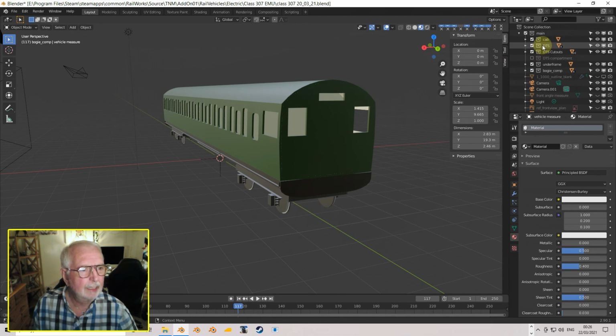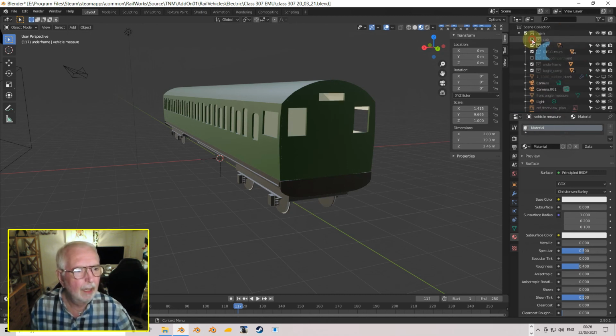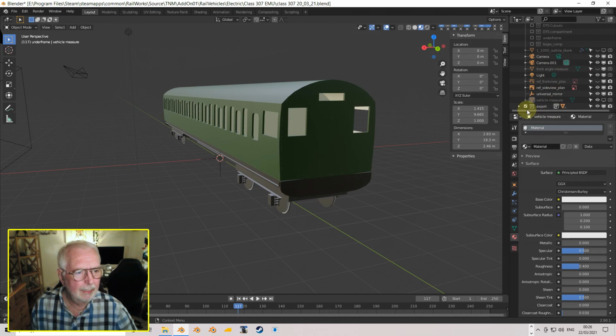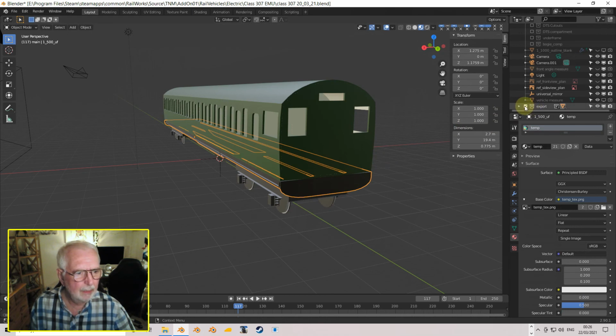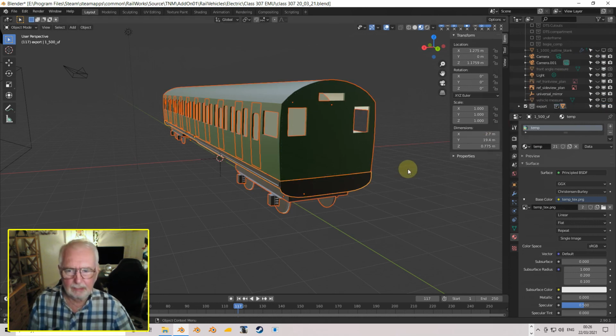So we just want the DTS. Okay, that's the only other one. Let's bring that down. Okay, Control and drop it in the export folder. So that's fine. So we can turn all these off. Okay, and then let's have a look, make sure. Yeah, so that is looking okay. Make sure nothing else is on, because if there's anything there that hasn't had texture applied or things like that, then it's going to throw an error up. So let's select objects.